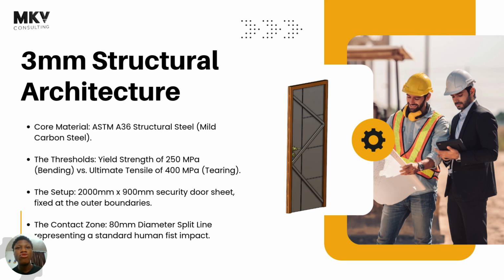The first thing an engineer should do is determine the geometry. That means making it less complicated and removing parts that are not important to your simulation, for instance fillets, edges, and chamfers that will not be valuable and will not alter the results of your simulation.